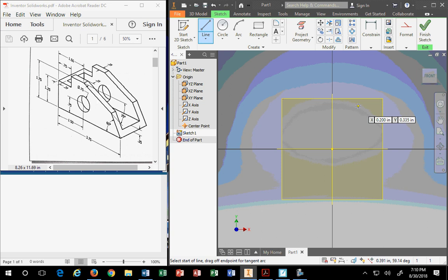Okay, if I build this correctly, my machining job will be a lot easier. If I build my part off in La La Land, my machine's going to see it off in La La Land. I got to drag it to the 0, 0 of the machine. It's an extra step, and some people say, who cares? But I am that lazy, so I care. By the way, lazy means efficient. Just translate it to the word efficient. When you hear me say lazy, just so you know.